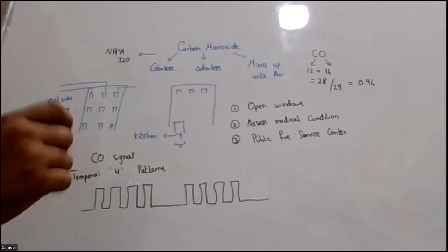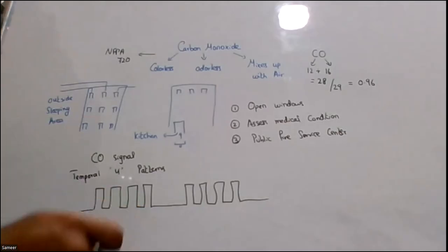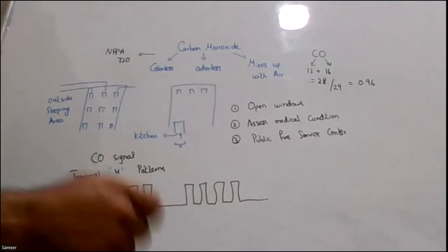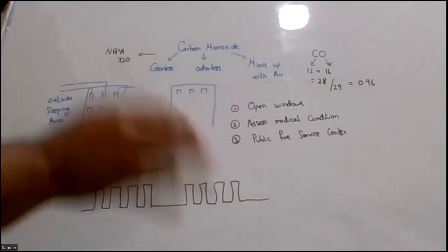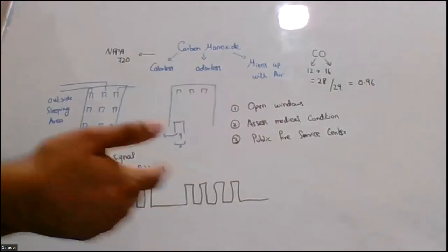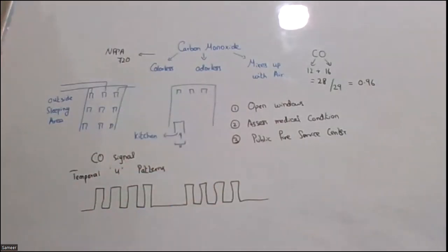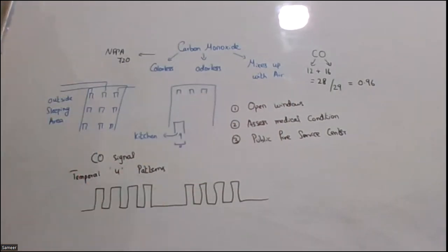So the bathtub curve gives me an idea of my failures, how many component failures there are, and whether I can depend on this system or not in the future. Usually the facilities managers calculate this for the future: in 5 years, 3 faults were there, so in 7 or 8 years I will get maybe the same, which is fine for me, we can work it out, it's not a headache. But if in the 5 years 15 or 17 components fail, it means the system is not reliable.